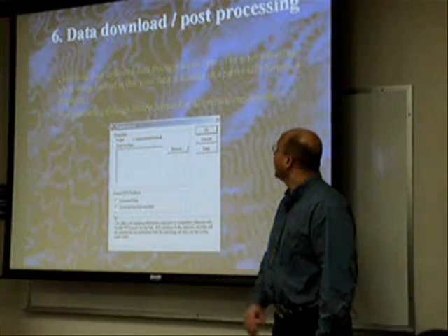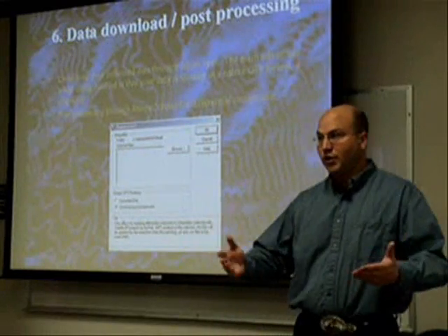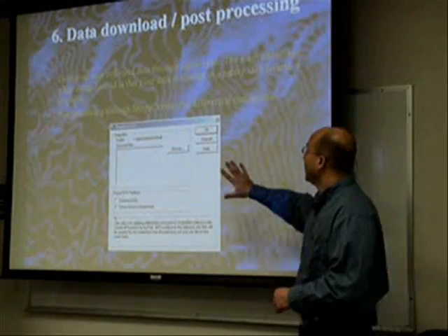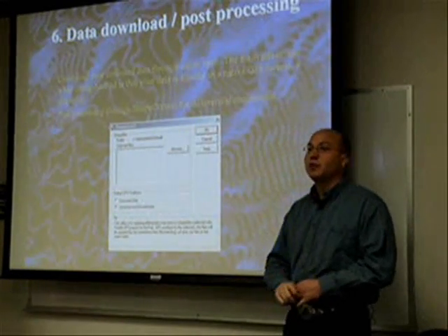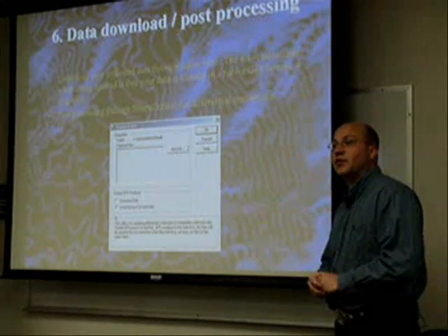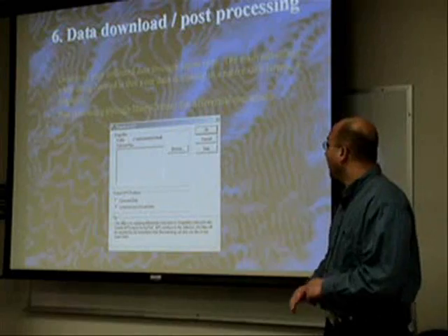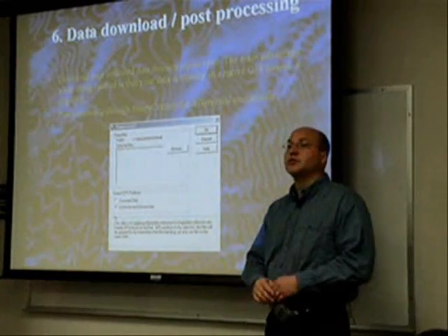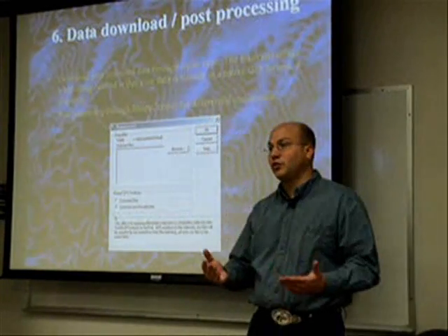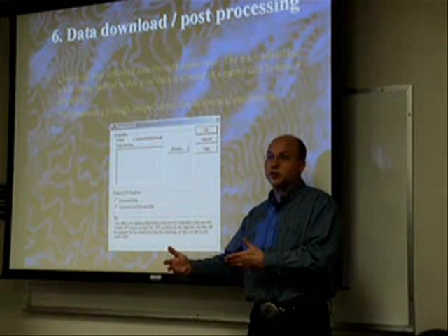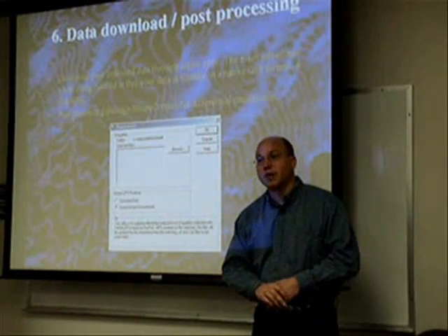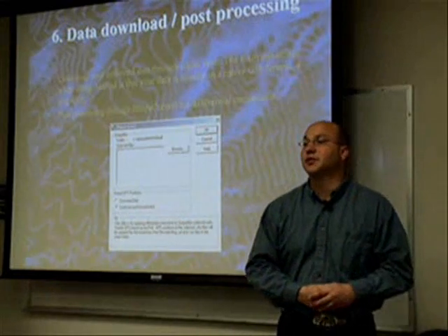Post-processing, what you might have to do, if you have chosen to select SSF files, is to go through Shape Correct. Shape Correct is, again, Trimble software through Pathfinder Office, and Shape Correct actually allows you to differentially correct shapefiles directly. So all you have to do is download the data that you collected, meaning the shapefile, get it through Shape Correct, and it's post-processed, differentially corrected.